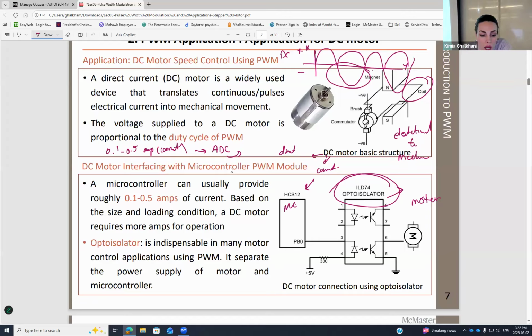That one is going to help you. You have to connect it to the motor. Tomorrow I'll teach you: you have to connect it to pin 4 and pin 7 and ground. Pin 4 is for channel A, pin 7 for channel B, because I have two channels in the setup. Use either of these, not both at the same time, plus the ground, in order to control the DC motor.